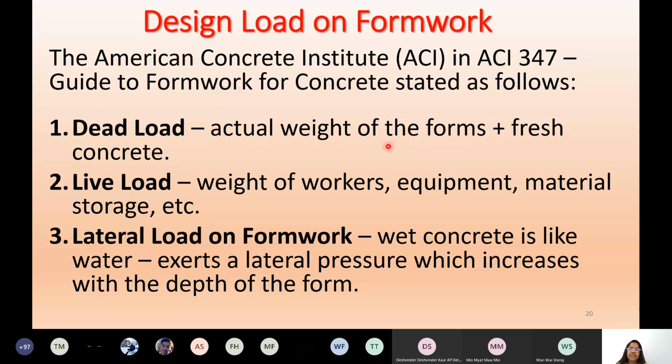Here self weight is its own weight, the power to withstand, right? So when you talk about the power to withstand of the structure as a whole, you need to consider both the form and the concrete, the shutter and the concrete. Form or shutters, we call these shutters, and the form is developed using shutters to pour your concrete. So the form or the shutters and the fresh concrete put together is called dead load.